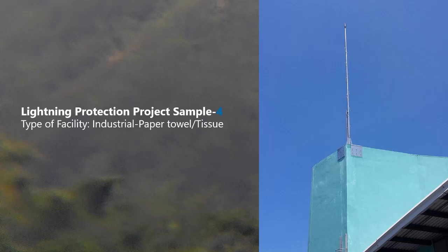That makes it easy for us to install the down conductor at the edge, in a straight path, because we want a lightning protection system without a bend or loop. We want it straight down to the ground. That's a best practice for the design of the lightning protection system.